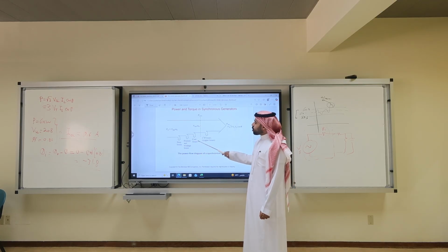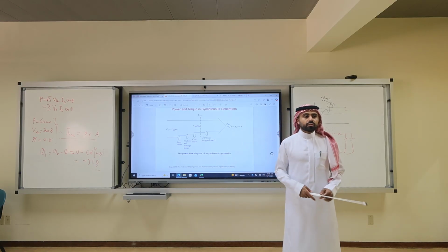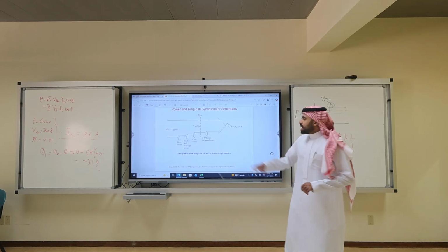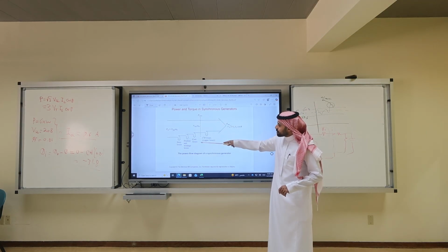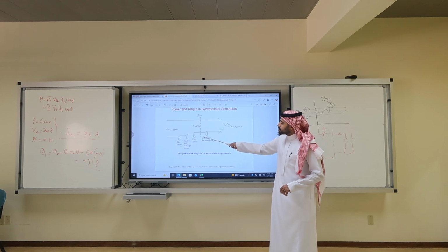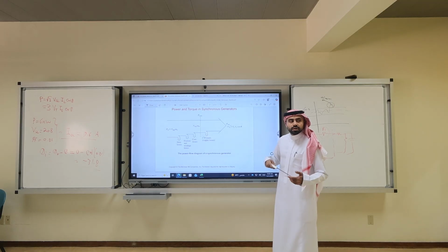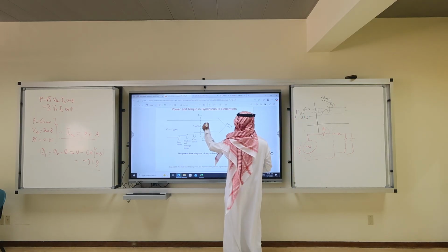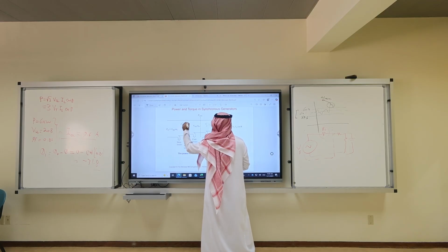I should have the core losses, mainly the air gap losses. Then I should have the developed air gap torque and air gap power. Then I have only I squared R losses, copper losses, in the stator. So this is the stator, and this is the rotor.